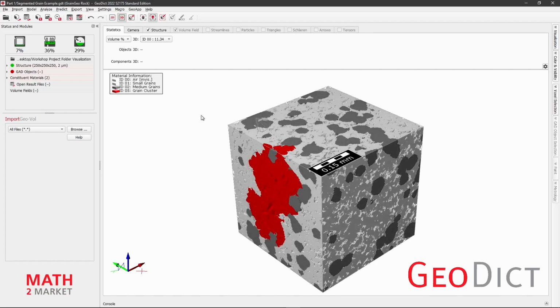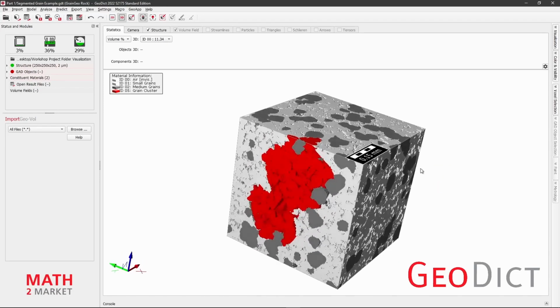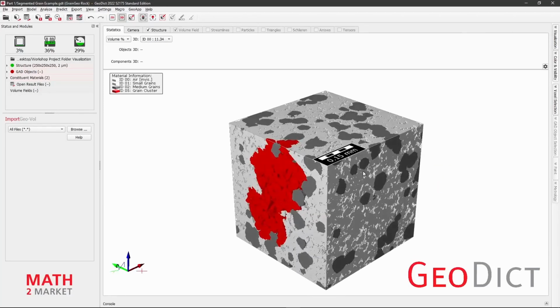We make sure that all sides are still clearly visible despite shadows, and that the shadow on the side here, the previously illuminated side, does not become too dark. So we adjust it roughly like this, and as soon as we are satisfied with the result, we switch back to the mouse mode with the toolbar icon here. And now we again can adjust the camera with the mouse.